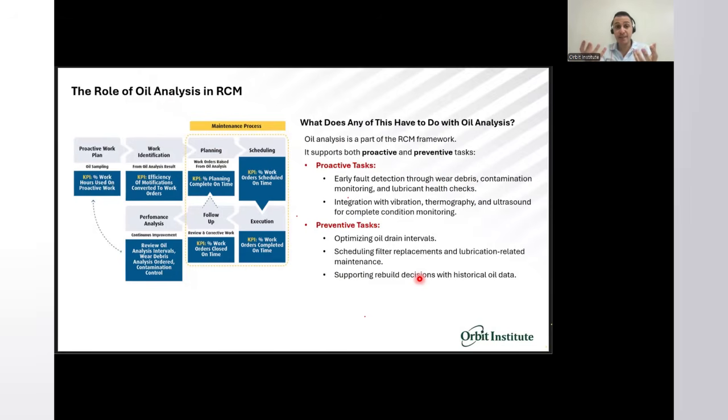So oil analysis can be used as a proactive task and a preventive task. If you use oil analysis for early fault detection through wear debris analysis, contamination monitoring, lubrication health checks, and so on, and integrate this with vibration analysis, thermography, and ultrasound to complete the condition monitoring and diagnostics in order to identify the root causes of the problem and then start to eliminate them, then this is a proactive approach of oil analysis.